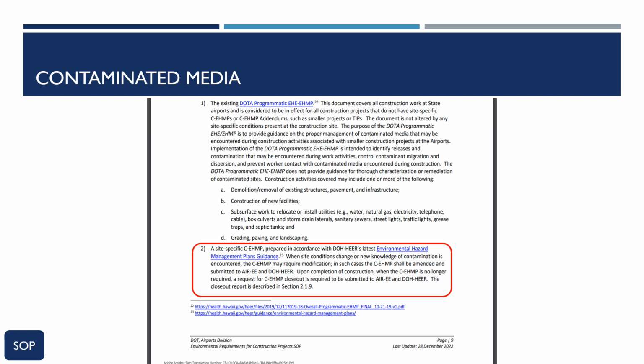The most common types of remedial action plans describe remedial measures such as the excavation and disposal of contaminated soil, storage tank and piping removal, and/or hazardous material abatement. Other remedial measures are designed to put long-term protections in place. These are most commonly impervious caps, vegetated covers, or vapor barriers over contaminated areas, and designed to prevent post-construction exposure and/or releases of contaminants to the environment.